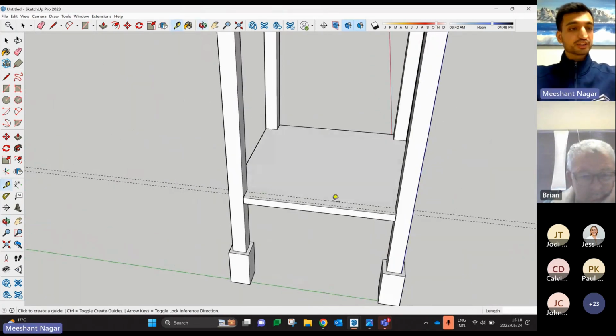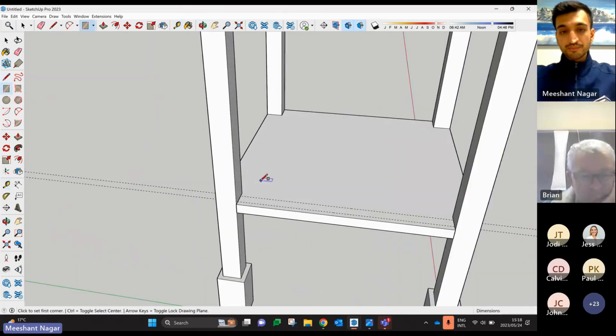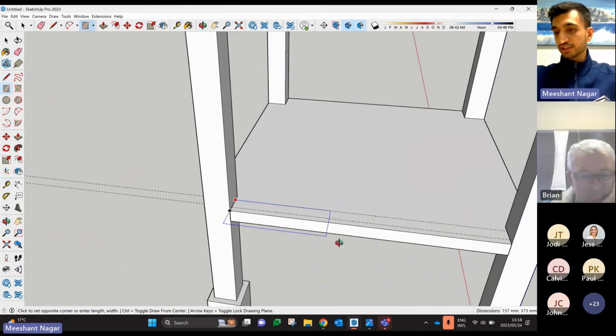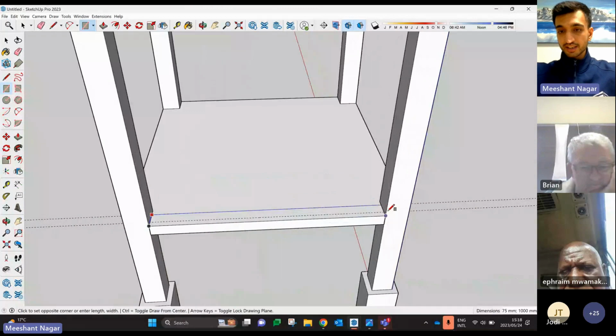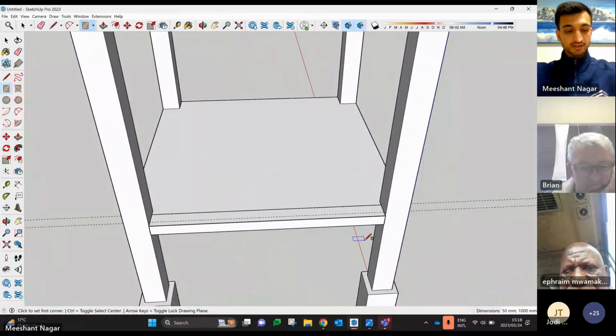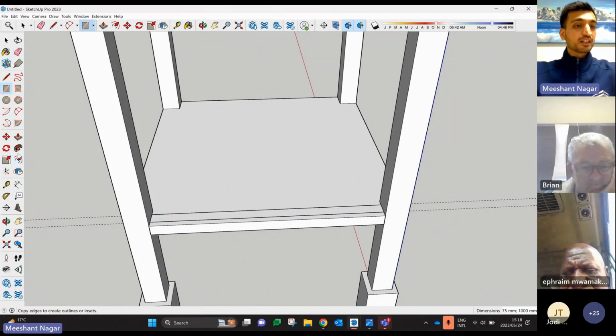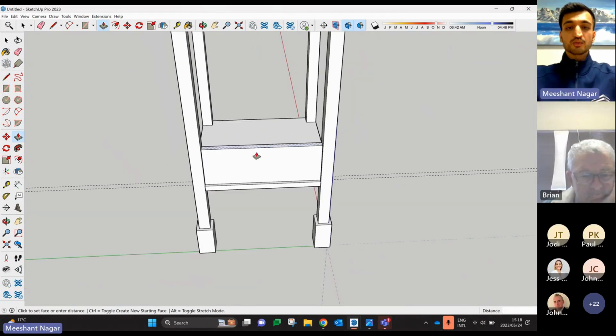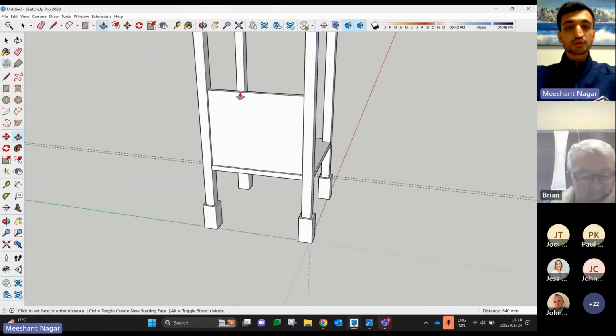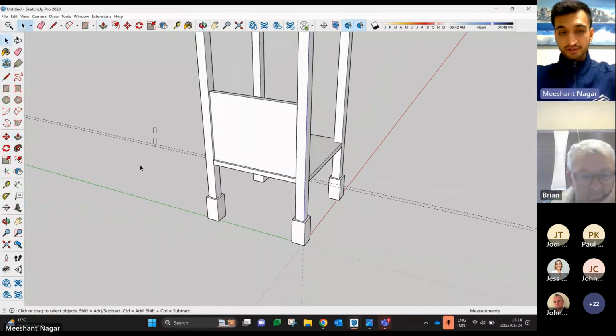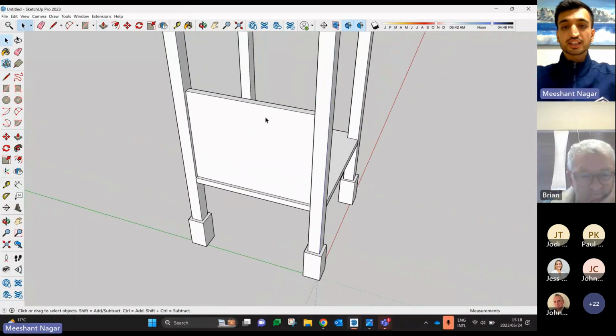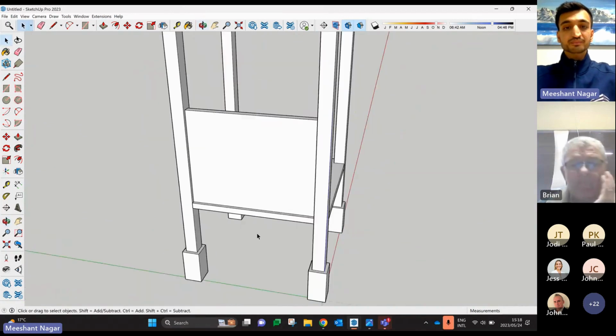And then that's, as you can see, that would be our wall. Put the correct dimensions in. I'm going to be adding a rectangle in there. Oh, sorry, misclick. Let's do that from there to there. And then dragging our wall up using the push pull command. Let's make it 800 high. Enter. Okay, I'm just going to delete the construction lines. And just like that, we have our wall in.